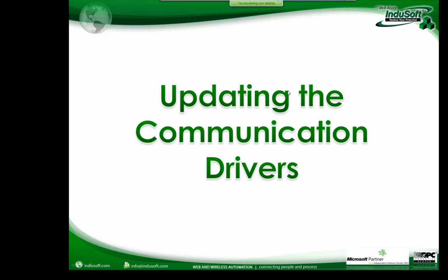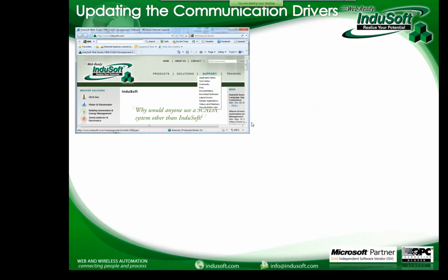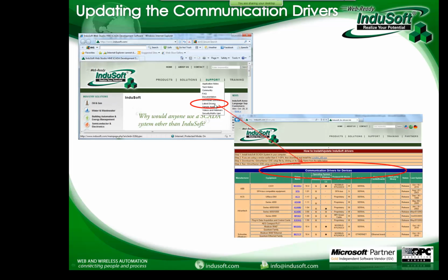Alright, so between InduSoft releases, we may update the communication drivers, we may release new functionalities, new versions with bug fixes and everything. So you don't need to update your entire InduSoft installation to update only a communication driver. You can go to our website. So you're gonna see the link support. Under the link support, you're gonna see latest drivers. Click on that link, you're gonna go to our drivers page. You're gonna find the link to download the driver.